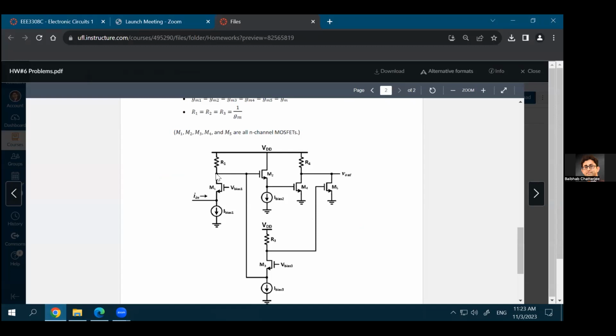But remember that gain, Gm times Rd, that's a voltage gain. In this case, what you are trying to find is a voltage divided by a current. So your input is a current in this case. And if your input current is this, the same current will flow through the drain terminal as well, because looking down, you'll see a DC bias current, a current source.